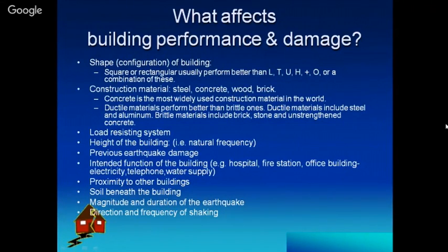You know very well that ductile materials behave very well because they give, even after an earthquake. After the initial limit state of the building, they let the building go through more displacement as compared to brittle material, which is going to collapse immediately, and the displacement is reduced. So with ductile material, we can have the collapse limit state, that is, you can have the time to evacuate or something like that, and that comes at the design stage.